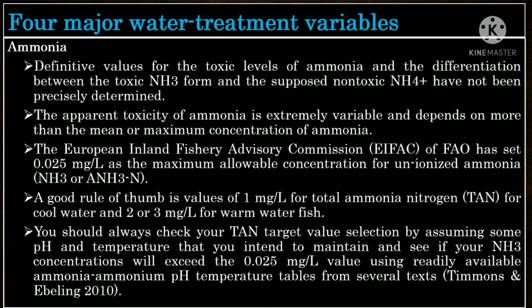You should always check your TAN target value by assuming some pH and the temperature that you intend to maintain, and see if your NH3 concentration will exceed the 0.025 milligrams per liter value, using the readily available ammonium pH temperature tables from several texts.